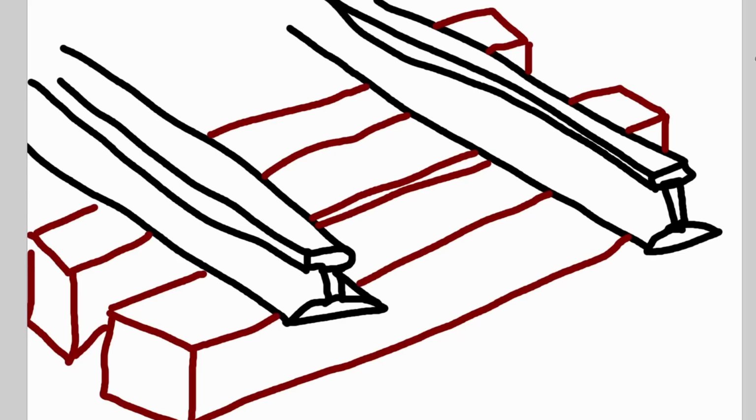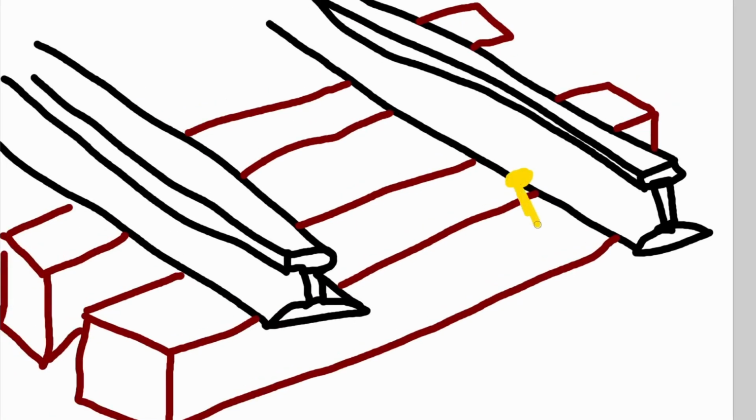Well, if you're in the UK, they're called sleepers, but here in the States, we call them ties. Historically, the ties have been made out of wood, typically oak or other hardwoods, though they tended to use whatever they could get their hands on in some cases. But these days, we also have concrete ties in a lot of applications as well. The ties are usually roughly square in profile, and you typically don't see the edges of them because the ballast is typically tamped down to about the height of the ties themselves. But they typically extend quite a bit off either side of the rail to provide support. With the addition of spikes that get driven into the tie, you can hold the rails down to the tie.